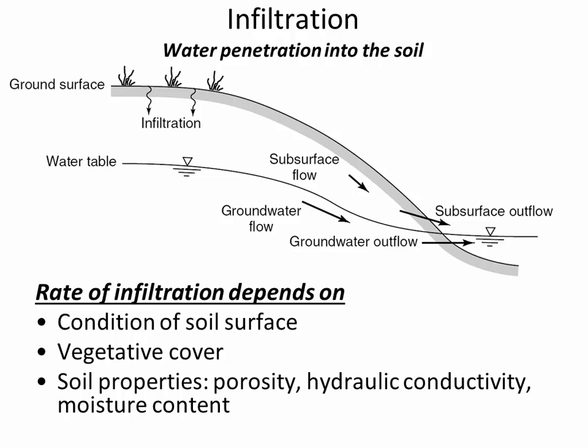And so it's kind of dirt, a little bit of grass, and the dirt is really slick because it's been stepped on so many times, it's been compacted. So there would be very poor infiltration on that little median strip of grass between the sidewalk and the road because there's not much vegetative cover and the condition of the soil surface is poor. And the other thing that we have to look at is the numerical properties that we can classify for the soil, like porosity, conductivity, moisture content, and so on.